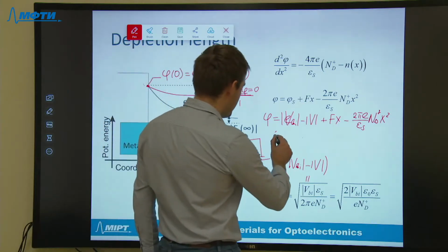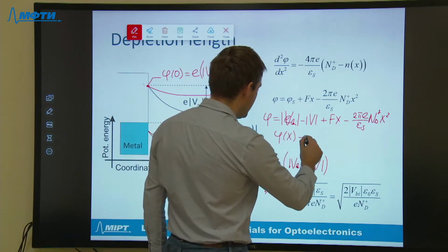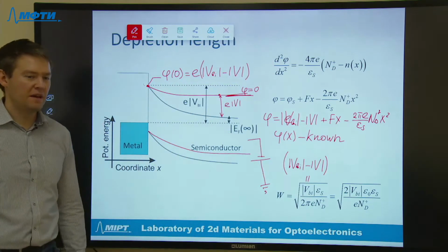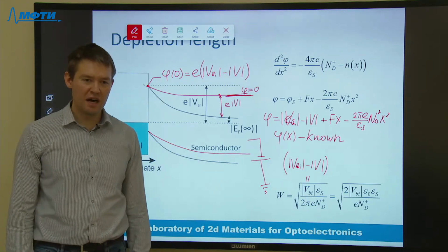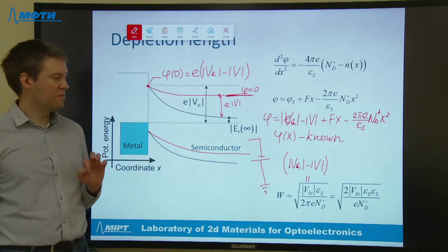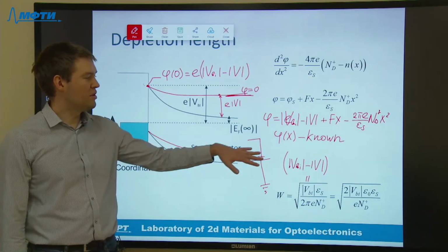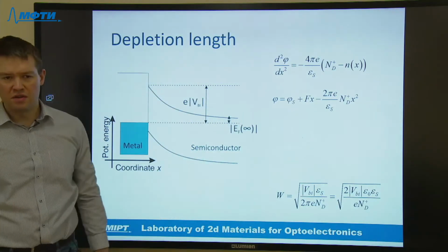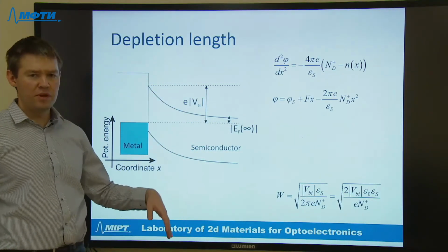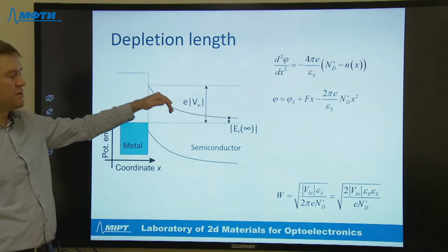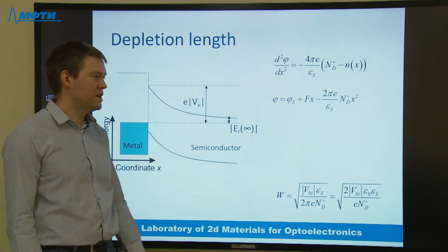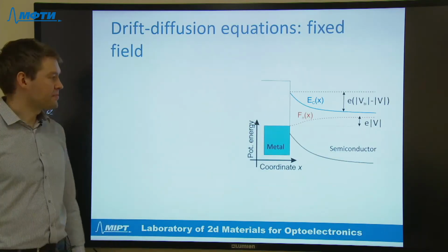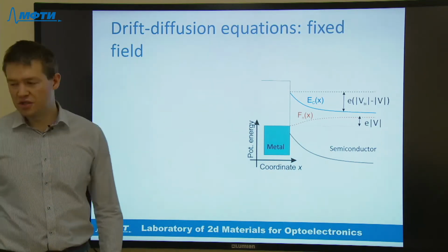So we assume that the profile of electric potential phi is known, and we will find the distribution of electric current, including the drift and diffusive components, under the assumption of known potential structure. Actually, it is not so simple as it may appear, because the background electron density is highly non-uniform in this junction, and you cannot apply simple Ohm's law. So what will we need to solve?